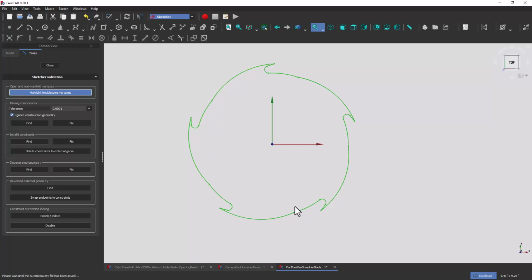I'm like, that's kind of interesting. They should all be the same. I was trying to make everything consistent. And sure enough, I had to go in there, and instead of the vertices being coincident with each other, one of the vertices was actually constrained onto the other segment. It was like an overlap. And so once I deleted the constraint, that freed them up, and I could pull them apart by like a micron of a micron, and then select both of them and tell them to be coincident.